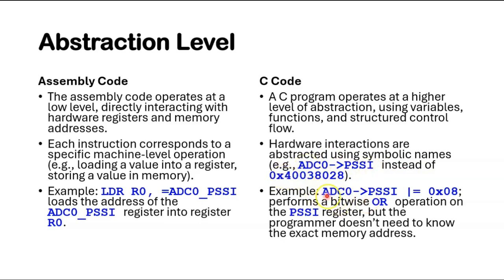Here is an example: ADC0->PSSI bitwise OR operation with this 0x08 value. The programmer doesn't need to know the exact memory address.